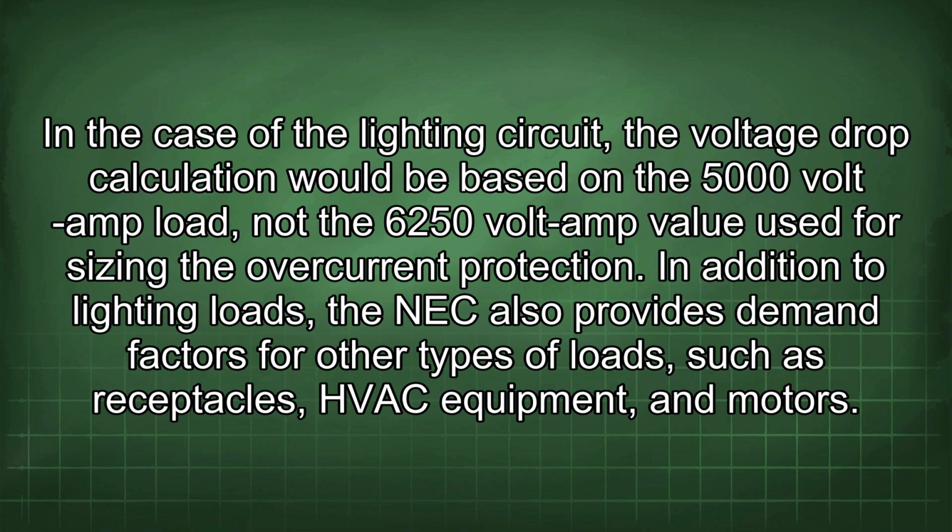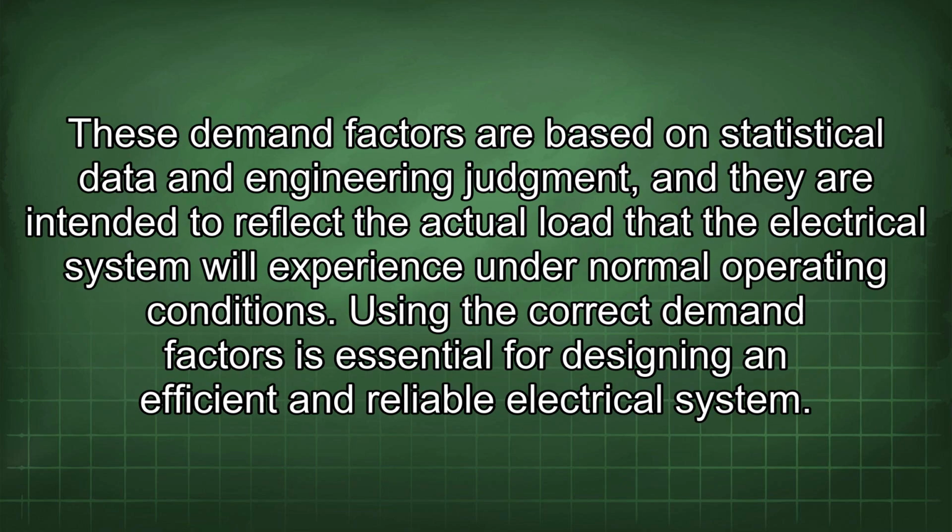In addition to lighting loads, the NEC also provides demand factors for other types of loads, such as receptacles, equipment, and motors. These demand factors are based on statistical data and engineering judgment, and they are intended to reflect the actual load that the electrical system will experience under normal operating conditions. Using the correct demand factors is essential for designing an efficient and reliable electrical system.